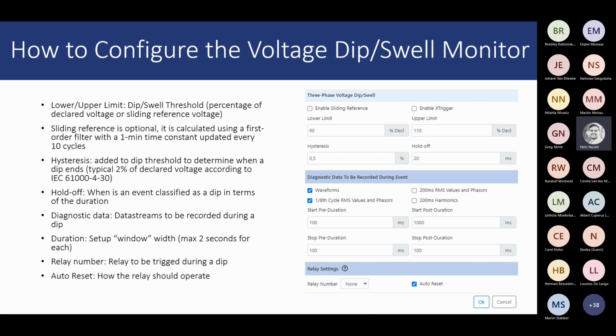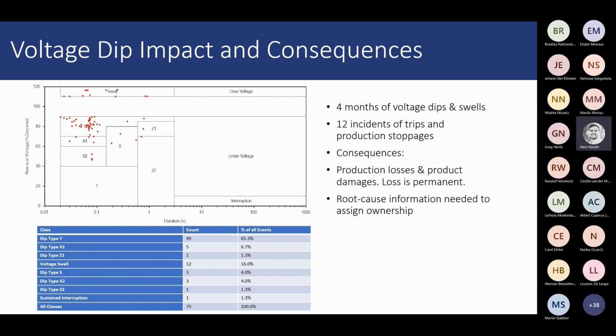And then the next part, may you also please address how to set those thresholds to appear on the graph on Osprey Lite 2. You cannot, unfortunately, from my knowledge, set that up on Osprey Lite on a graph, on trends. On the reporting, from what I understand, you will get a scatter plot that will show you a graph like this that shows you where a specific event is compared to those thresholds. On Osprey Pro, however, we do have a function to plot a trend where you can specify a limit. I will show that to you also in the demonstration so that you have an idea of how to do that, if you're interested. I hope that answers your question.